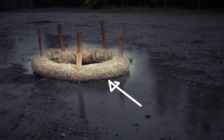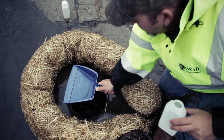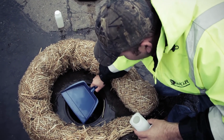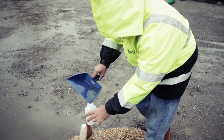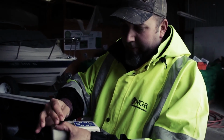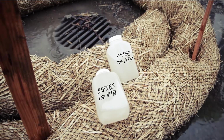Now, if you installed the fiber roll correctly, as specified in the CASQA and the Caltrans fact sheets, you would probably get much better numbers, but then again, how many times have you been on a job site and seen it installed just like this? We wanted to see how the fiber roll would perform under average installation conditions. We also installed some fiber roll around the drain inlet in a nearby parking lot. So after waiting about 30 minutes for any sediments to settle down from our installation activities, we came back and carefully collected samples from both of the drains and tested them in a calibrated turbidity meter. The results are pretty surprising. The turbidity after the straw water was actually higher than it was before.